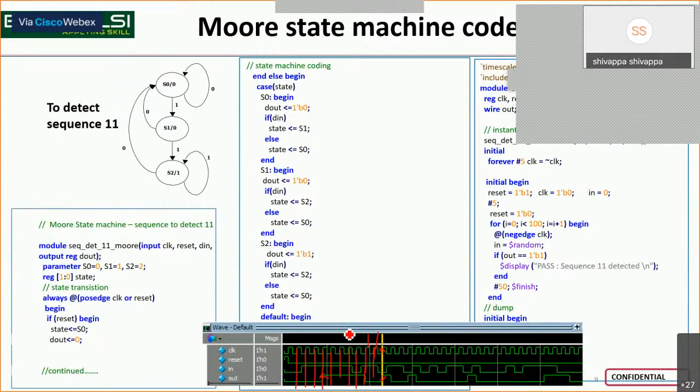Most of the time, Moore state machine is good, though you are using additional gates. In a Mealy state machine, input transient filtering is not happening, so that way Moore is used more. Nowadays, these kinds of optimization techniques at the coding level have shifted to backend optimization and device manufacturing level rather than the design level.